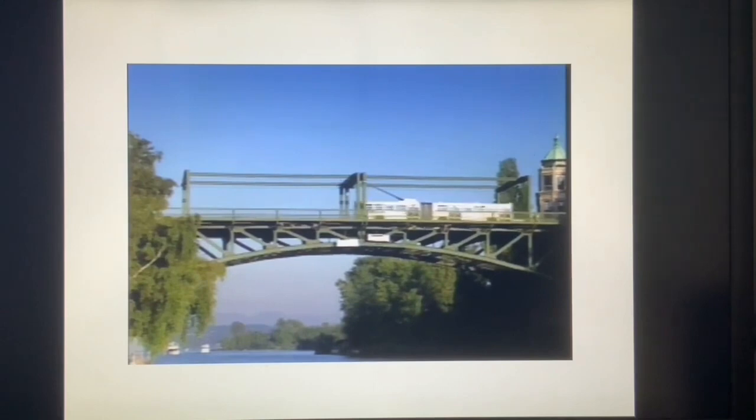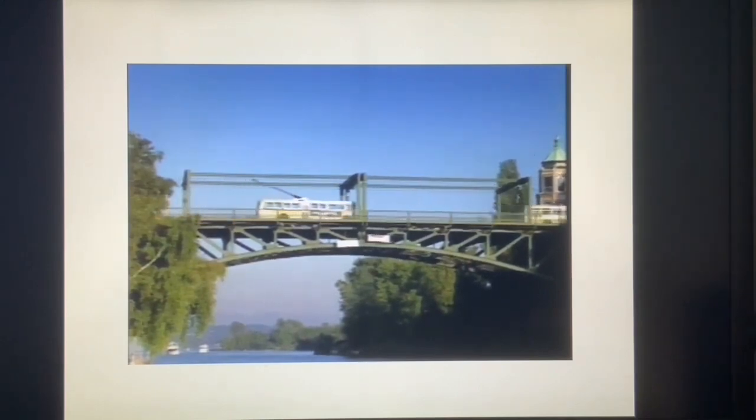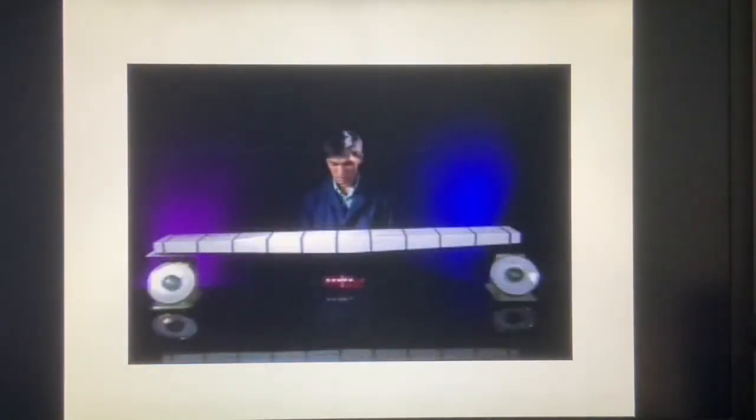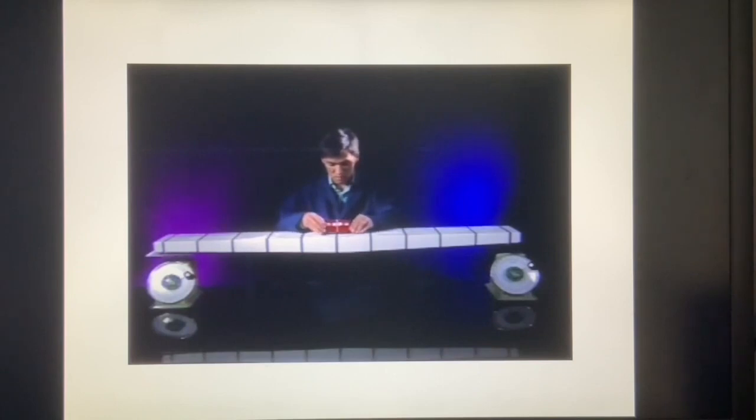Do the forces supporting the ends of a bridge change as a heavy bus moves along the bridge, or are they always the same? This demonstration uses a model bridge supported by spring scales and a heavy toy truck to find out. When the bridge is empty, both scales supply the same force to support their end of the bridge. If the truck is placed in the middle of the bridge, the scale readings increase, but are still equal.